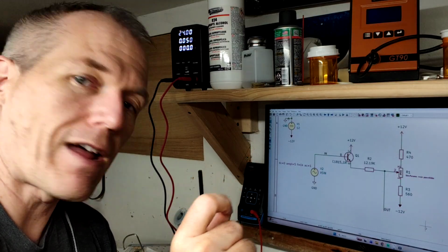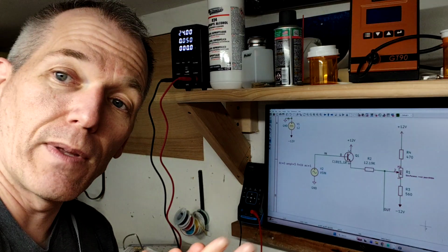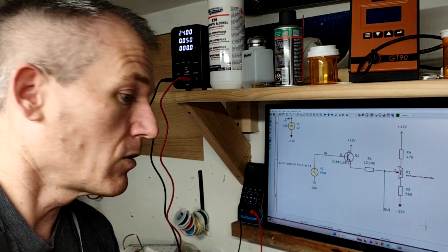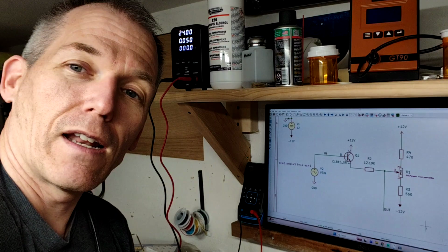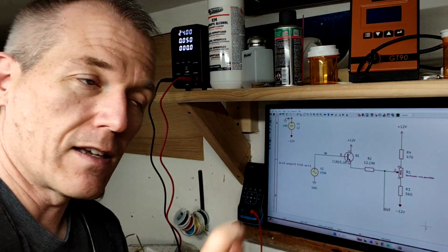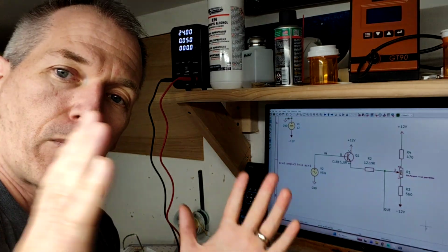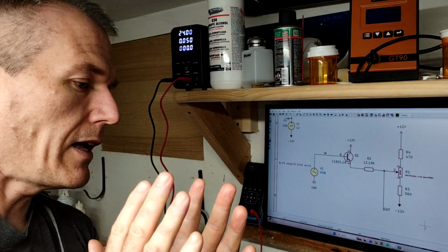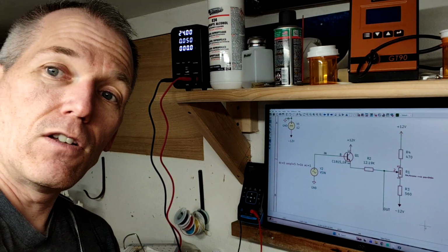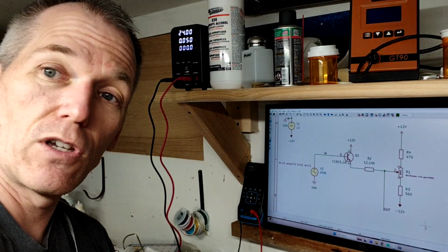And that will be the kind of active region of the transistor that is going to create the exponential function for our volt per octave circuit. But first we have to go from this plus or minus 5 volts to something that has a smaller range and an offset to it. And we can create that compression of the voltage as well as the offset by creating a little network of resistors. It's the simplest way to do it.